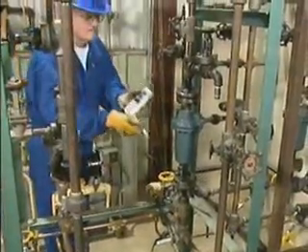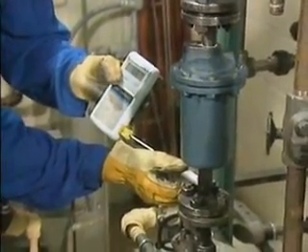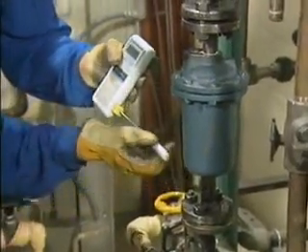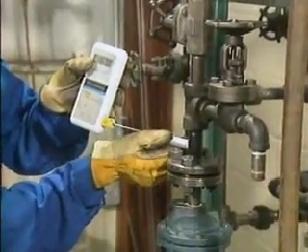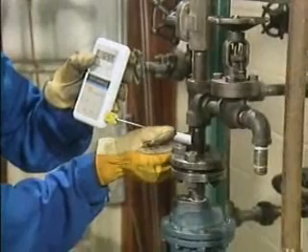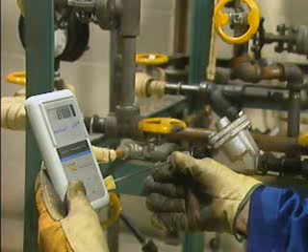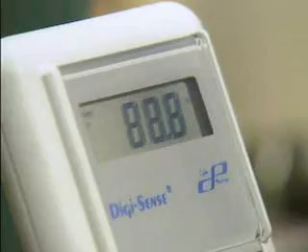A temperature inspection is usually a good starting point for a trap survey. The temperature at the trap's inlet and outlet pipes should be in the normal range for the specific trap installation. Generally, the inlet should be hotter than the outlet, but if the outlet is cold, it could indicate that the trap has failed closed. Whatever method you use for a temperature check, you must be able to interpret the meaning of the information that you obtain. For example, a properly functioning steam trap is usually warm because live steam is unable to escape from the trap, while a cold trap is probably not working.